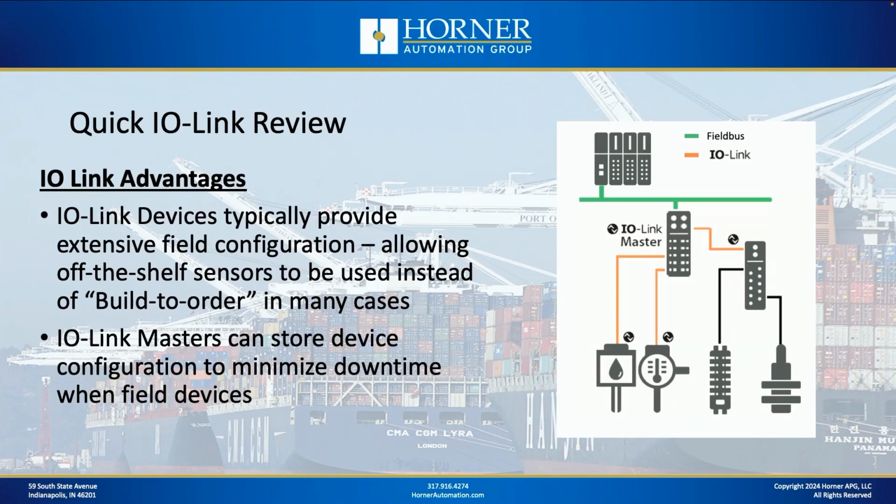And another advantage of IO-Link is that the masters can actually store the configuration for the smart devices that are connected to them. So if you ever have to replace one of those IO-Link smart devices, the master can reprogram them automatically to minimize downtime.